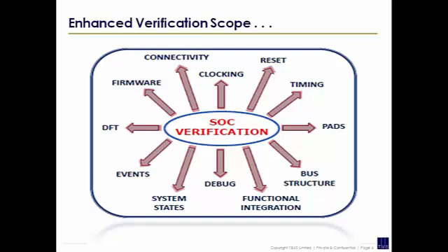Okay. Now moving to the next slide. This is the summary of the previous 2 slides. Modern SoCs have become so complex that simulation alone cannot verify enough of the design state space. We must use multiple verification strategies in concert to achieve the goal. The new approach would involve a hybrid verification environment comprising RTL simulation, gate level simulation, formal verification, and emulation.